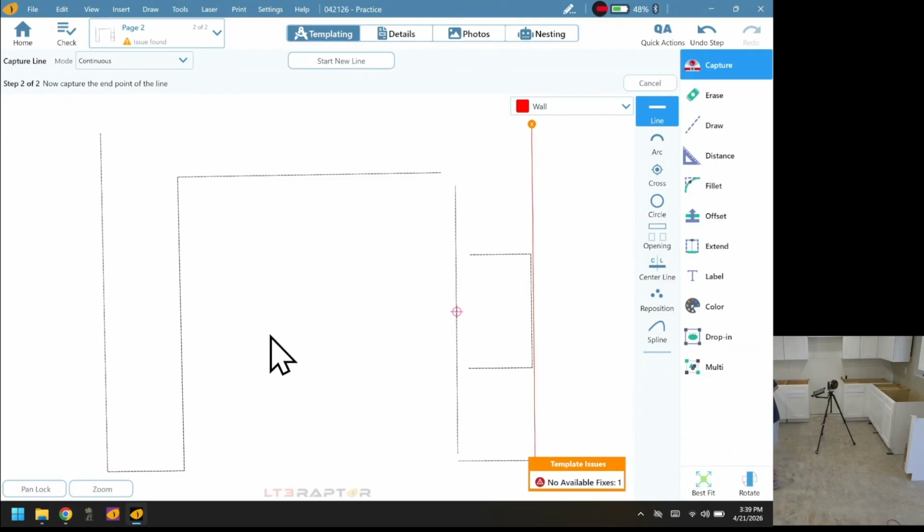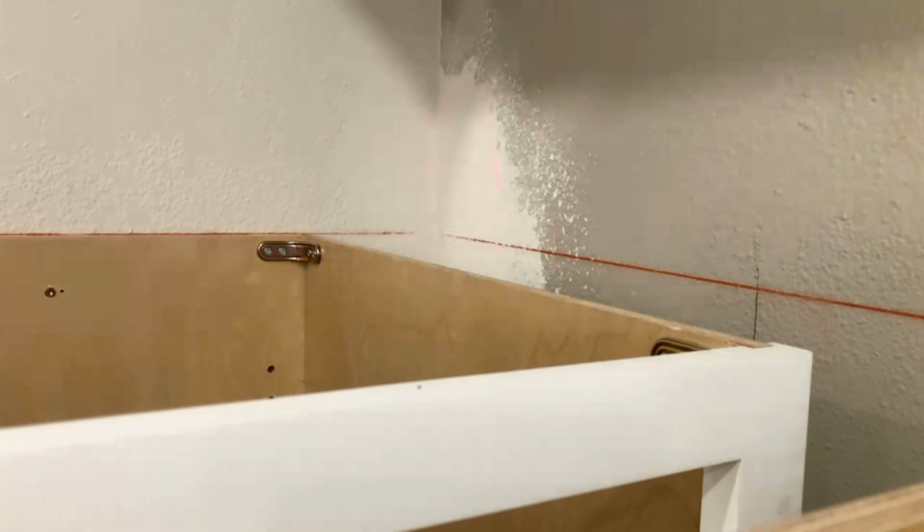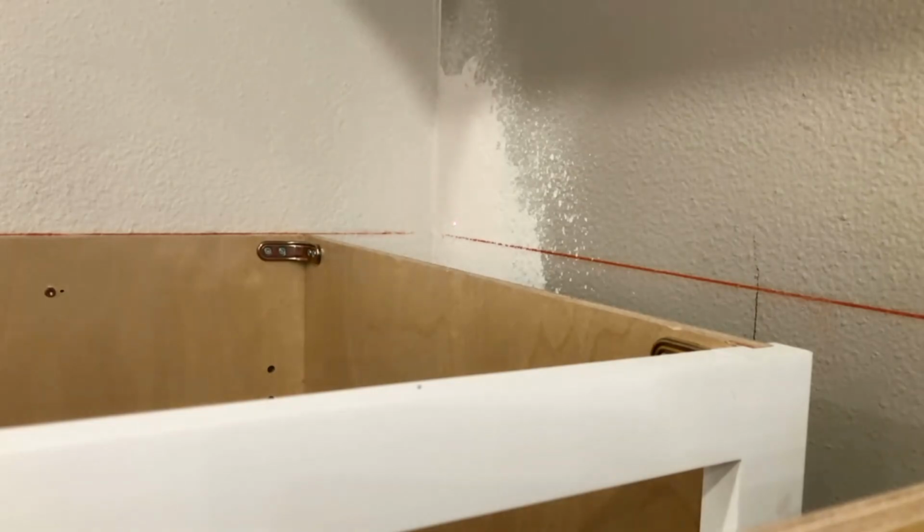I think this is important. I just patched this. I didn't get time to paint it yet. So it's not perfect. It's kind of ugly, but I think the concept is still there. How do we capture a drywall corner, right? So you can see this wall has a big patch here. This will be painted so we can see more difference later, but that's just not done yet, right? So as we capture, I want to get to about 3 inches out of a drywall corner, okay?